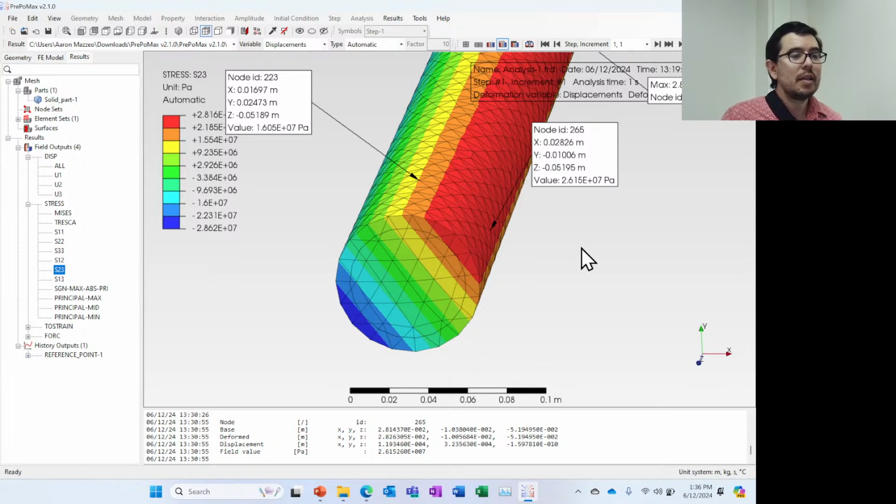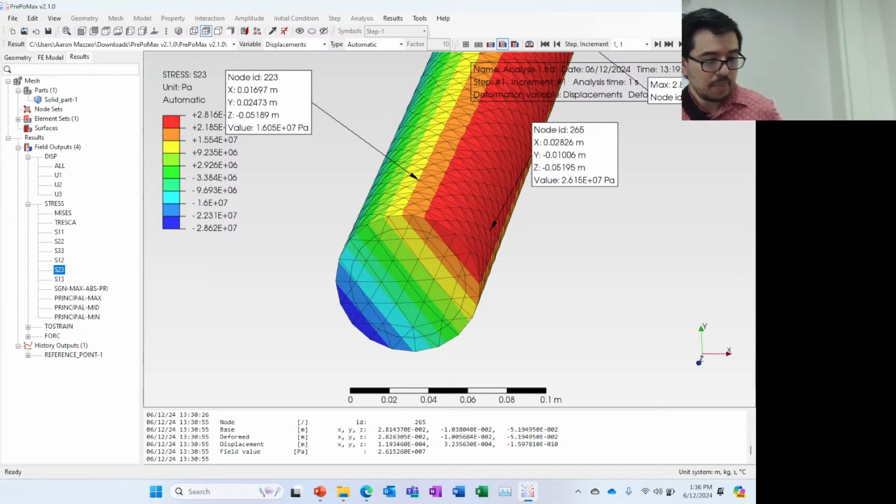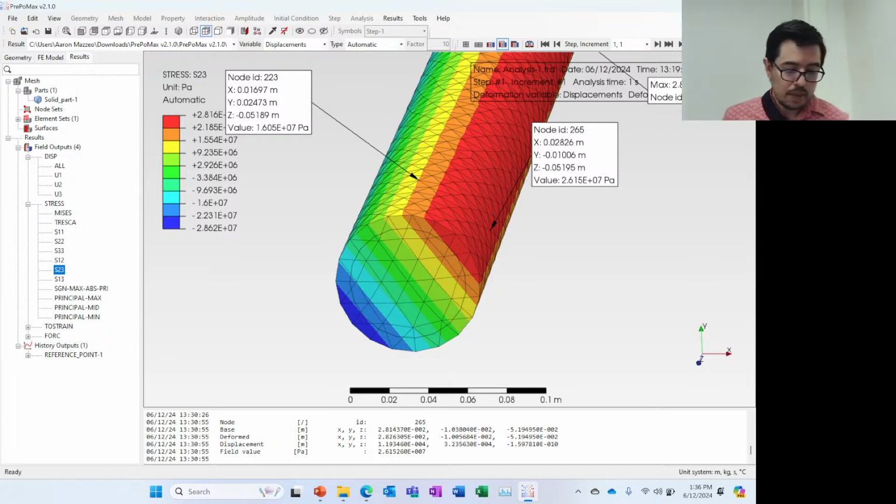So I had problems with my homework. When I imported it along the z-axis, in order to get the x strain or whatever, I had to pull the 3 3. I forget how it was, but if I wanted the x value, even though it was running along the z-axis, I had to pull s3 3. Okay. That would make sense. Maybe there's a bug that was introduced in this version, because I don't remember this happening before. In fact, I tried to rotate the cylinder into X, and now it's coming out in Z. Yeah. And I'm getting confused about what is what here.